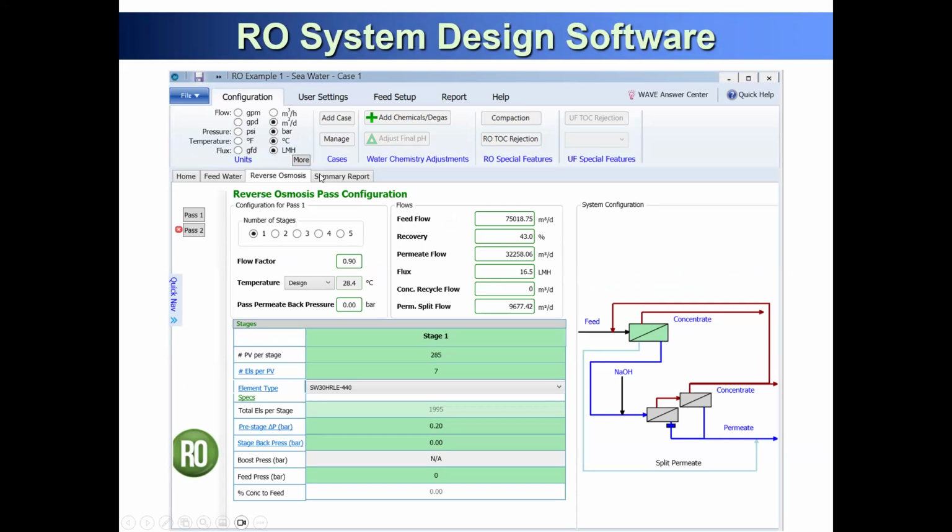Already we tried 720 cubic meter per day, which required 8 pressure vessels. Then we went for a 2-to-1 ratio and 6 pressure vessels. Now we design for 70,000 cubic meter per day. 700 was the 6 pressure vessels we needed, brackish water, right?